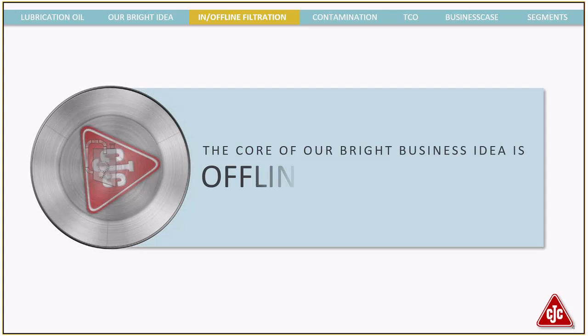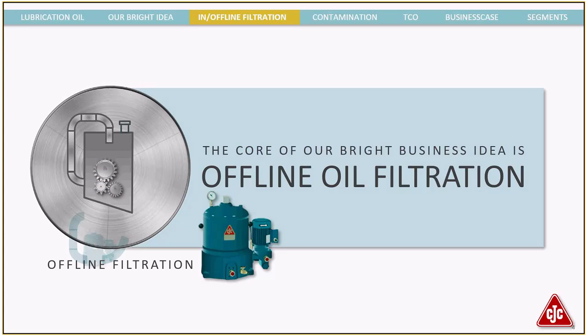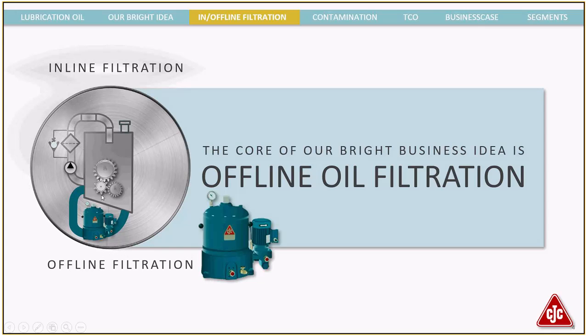The core of the business here for C.C.JENSEN is working with what we call kidney loop or offline filtration. We are drawing the oil from the bottom of the sump, so the gearbox, the tank, the hydraulic system, the turbine, and running it slowly through the filter in a depth media that takes a lot of dirt, a lot of water, and varnish out. It cannot be compared with inline pressure filters, because they live a very tough life where every start and stop, or control valves being moved, gives a pressure shock in the system and actually creates a release of particles in the inline filter.